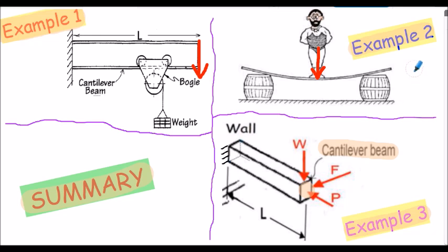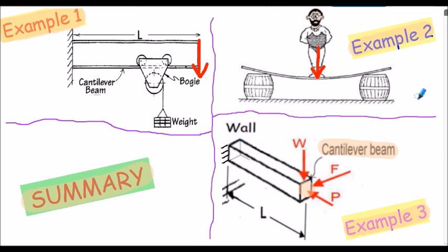So as the load on the beam was doubled, the stress was doubled, the factor of safety would be halved, and the deflection would have been doubled, which would make it now unacceptable compared to the allowable deflection of span length divided by 200.